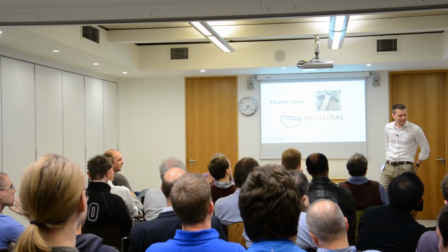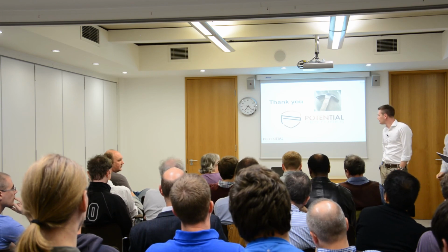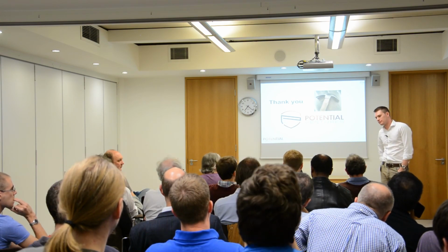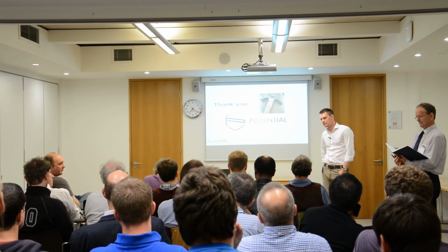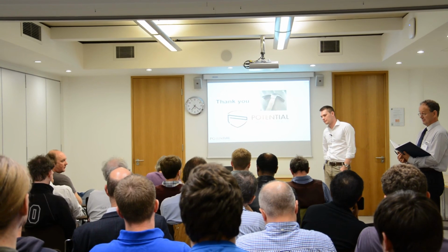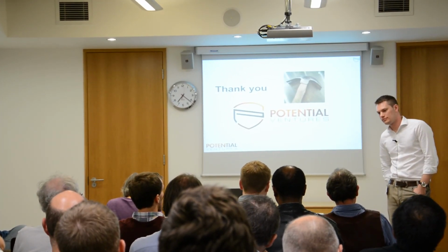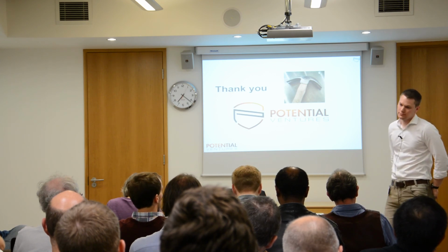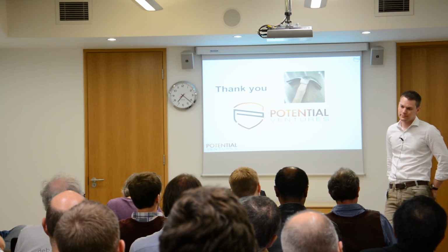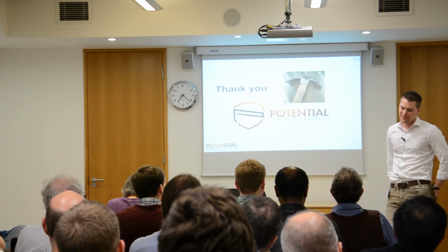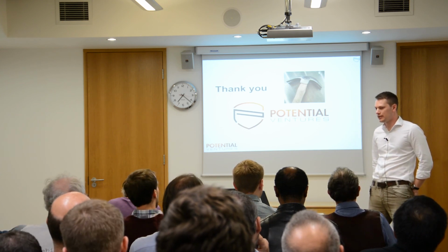I think the next talk might actually also touch on high-level ways of specifying certain qubits. So this has been a big gap in open source hardware design for a very long time. I applaud you for taking this on, making it accessible. One of the things I think this would go well with is Verilator, because that's actually quite fast for synthesizable stuff. And one of the problems with Verilator is that you can't compile non-synthesizable Verilog. Are you compatible with Verilator? I haven't tested it. So if it's PLI compliant, then yes.